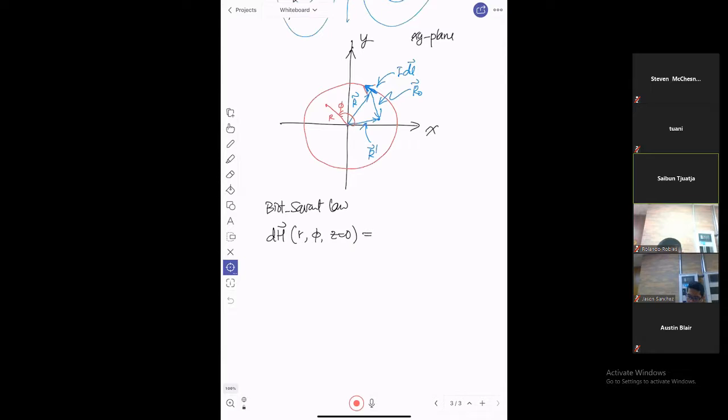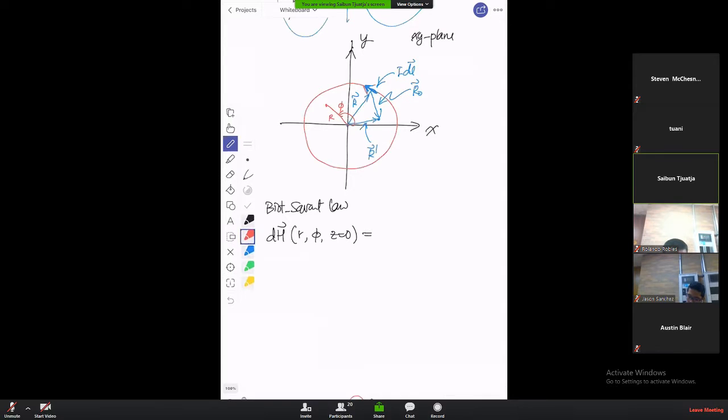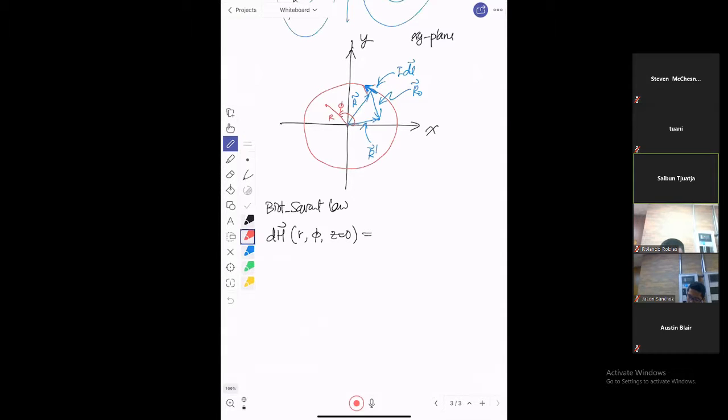All right. So now these are the differential elements at any point. So how do I solve it? What is the differential element? Well, according to the Biot-Savart law, this is equal to I dl cross with, now this is what's messy, the vector R, I call this R prime, the location of this, right?